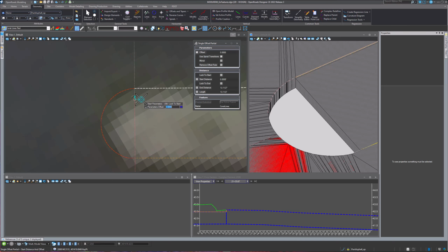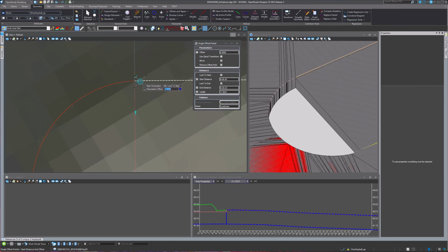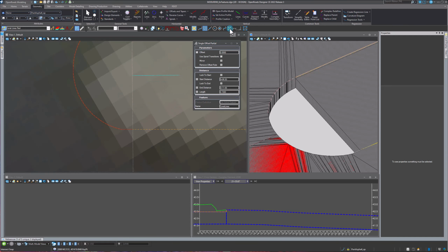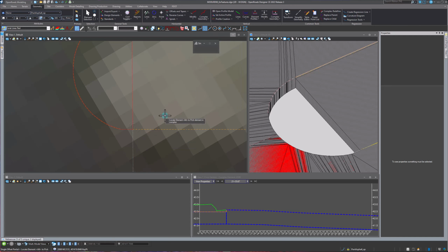And then I'll do the same thing along here. And I can just snap to the end of that line since that's where it's stuck anyway. You can either use intersection snap or snap to the end of this line. We'll just use intersection snap, and I want to make sure that the construction line's white dash and the traffic separator existing lines are the ones that highlight, so I can get that snap there.